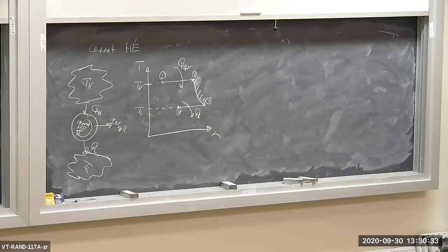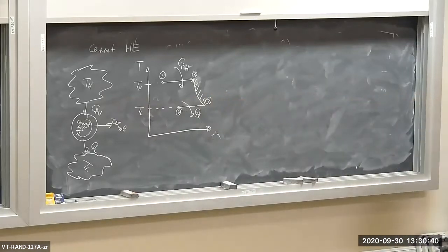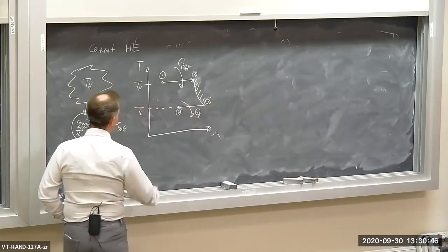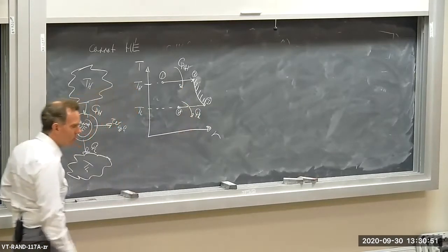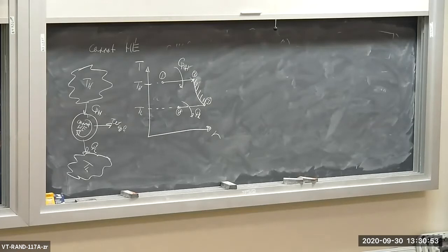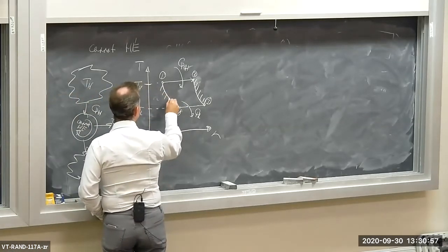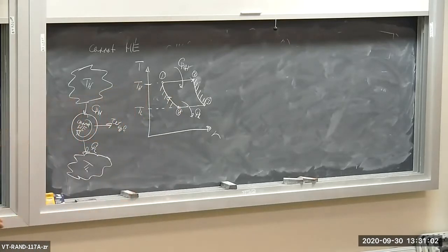Again, the working fluid inside the Carnot heat engine, our piston cylinder device, operates frictionlessly and slowly, so there's no unrestrained expansion and no heat transfer across any finite temperature differences, because all the heat transfers occur at either the high or the low temperature reservoir temperatures. Then we complete the cycle by having adiabatic compression back up to state 1. So that's the Carnot cycle for a heat engine.